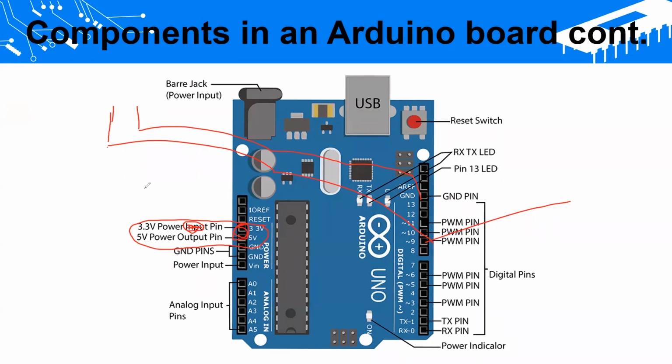But if you plug into this kind of voltage pin, that basically gives a constant voltage. You can't program these voltage pins or ground pins. You can only work with the digital pins and the analog pins. You have a set of functions to do that, and by using those functions you can implement several behaviors. Is it clear?